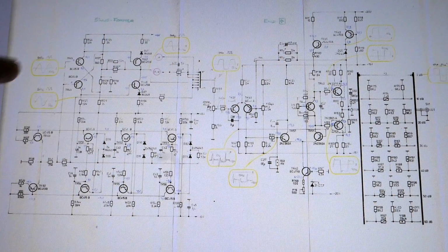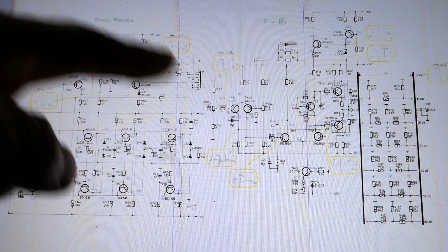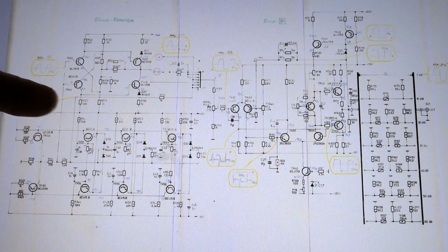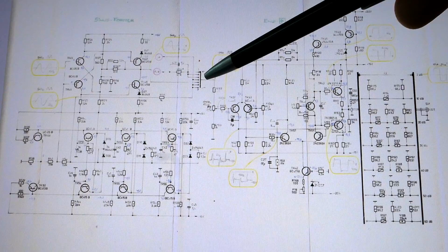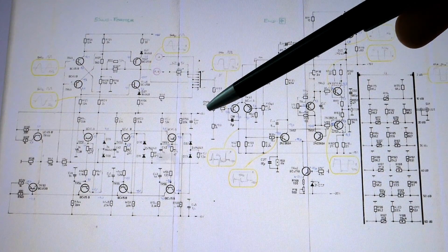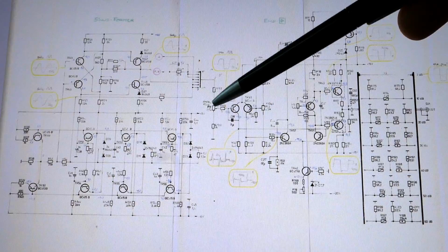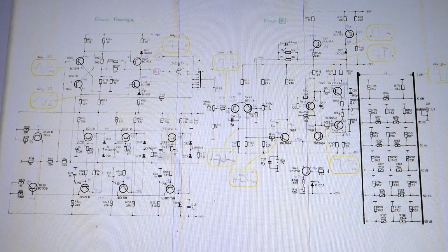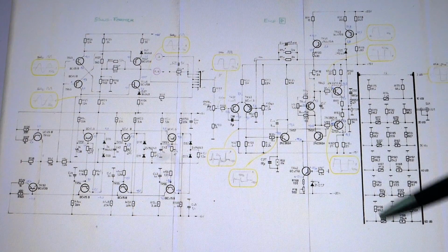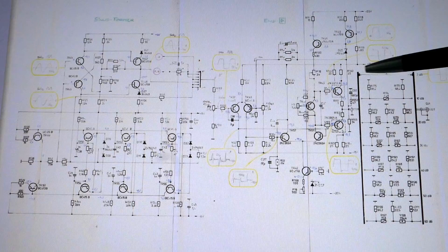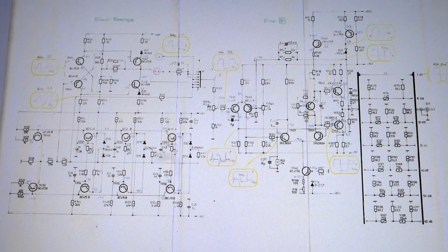And in this one, these 12 transistors are just to produce the sine wave. This is a crazy contraption. Basically the triangle waveform goes in, then a miracle happens, and then a sine wave comes out. This is only used for the sine wave and for nothing else. Otherwise this waveform switch gets directly the square wave or triangle wave and sends it into this fine amplitude potentiometer and this amplifier. These are the transistors with small heat sinks and then this attenuator resistor network. The amplitude switch can choose this straight connection or 6 different resistive dividers.